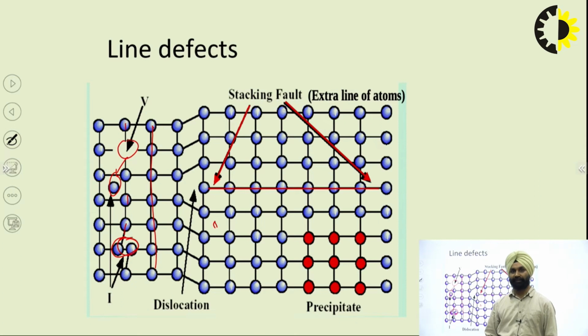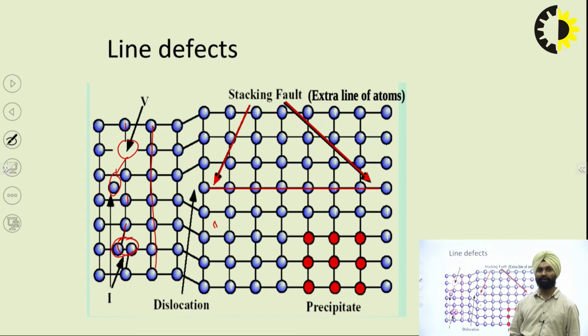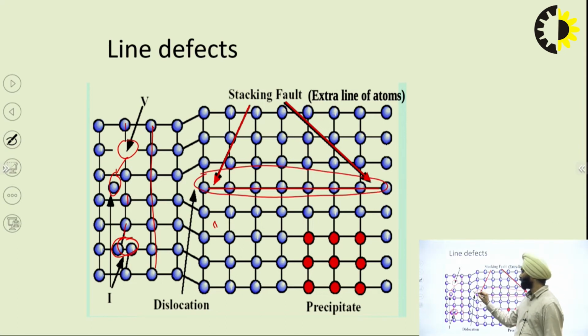Another possibility is that when we are heating up the crystal for the CZ method, the layers that are coming up within the CZ method are pasting or coming up with the lower layers. So when they are forming with the lower layers, they may create some extra lines due to the thermal stress.